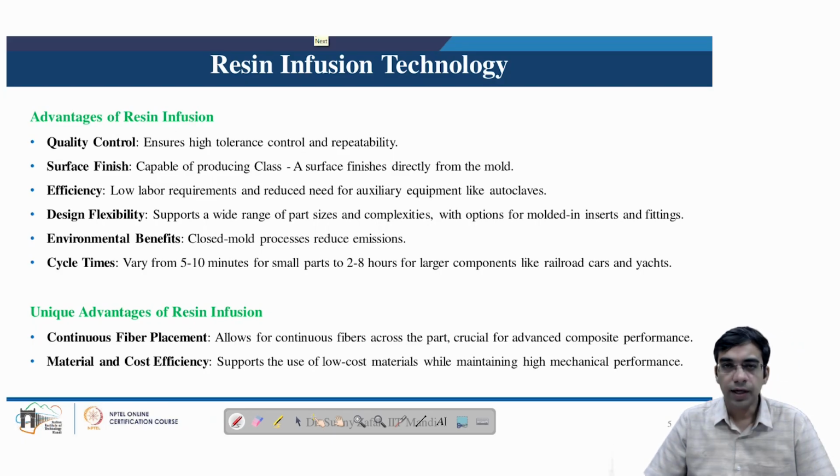So there are several advantages with the resin infusion process. These advantages primarily include quality control. Because of the higher injection pressure, the process ensures high tolerance control and repeatability. Surface finish is another advantage of the resin infusion process, which is capable of producing class A surface finishes directly from the mold.